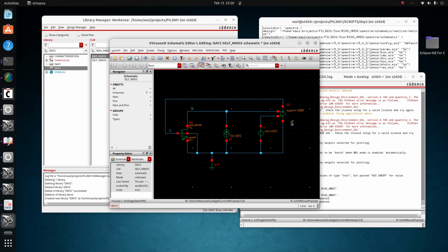So how does it work? This works pretty much similar to an op amp. Okay, it has a very large gain, and the output of this very large gain amplifier is going to be connected to the gate of the transistor. Remember that this transistor, now connected as a common source amplifier, will have a signal inversion from the gate to the drain, meaning that this system has a negative feedback. Okay, so it is a negative feedback system.